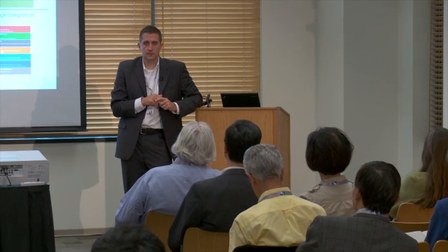So the first one, we talked a little bit about. The industry has looked at the CPs of horizontal axis wind turbines as being significantly better than vertical axis wind turbines, and really has gone down the path of 3-bladed. There are some places where you might see a 2-bladed machine, but 3-bladed is where the industry has converged, and it's very difficult for me to see any major change off of that. The vertical axis ones have a lower CP, so for them to compete with the horizontal axis, they would need to be a lot lower cost, which today they aren't.